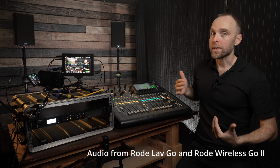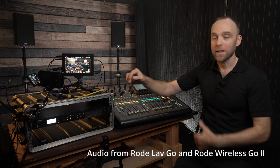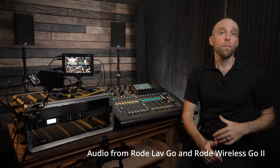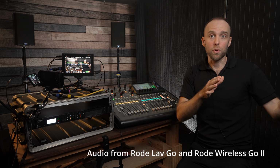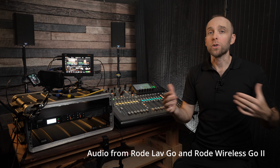Now, yes, you should always leave headroom. Headroom being enough so that if your talent gets louder, they don't clip out the receiver, they don't clip out the preamp, and headroom to be able to turn up those speakers from the console. But leaving headroom is part of gain structure. You're structuring the entire system, not just individual or disjointed components. You have to think about all the components in the system when you're gain structuring.